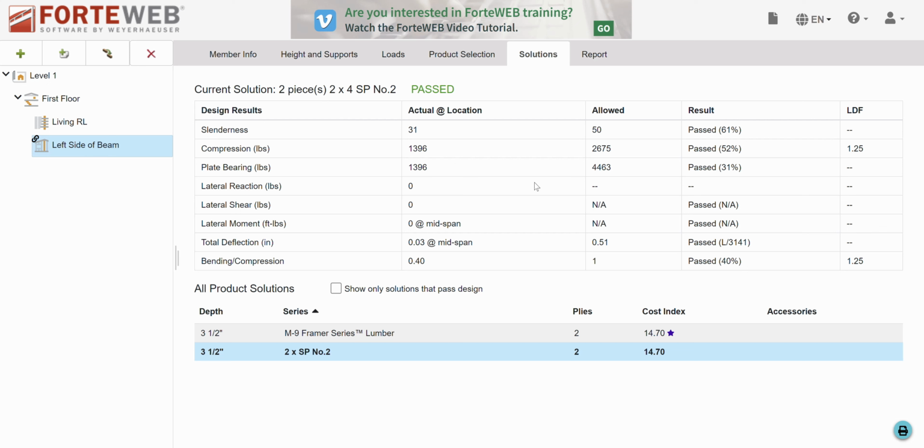Now, the general rule of thumb is you want solid wood from your beam all the way to the foundation. So if my beam is 5 inches wide, I would have to use 4 studs to get at least as wide as my beam in the wall. That's the general rule, but you want to check to make sure that's still enough. Sometimes you need a 2 by 6 wall instead of a 2 by 4 wall for the load capacity. But in this case, 2 studs, I'm good.